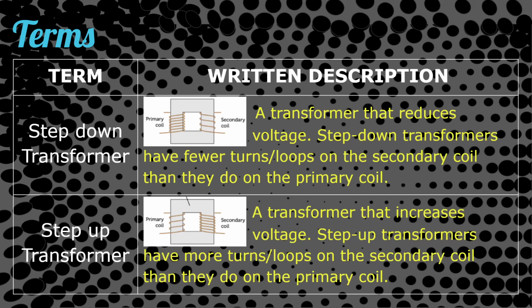The primary coil is wherever your transformer is connected to the actual electricity source. That is going to carry the voltage into the transformer on the primary coil side, and then it's going to flow through that coil, and it's going to induce a current in the secondary coil, even though they're not physically connected. Just like we looked at in the Faraday experiment earlier.